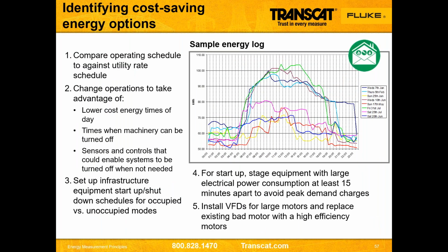So we want to look at a cadence or usage of power. When's my peak demand time? What loads are on or off during that time? What things are cycling on and off, like a compressor, for example? And where could I possibly install things like a soft start or a VFD to reduce the overall, what we refer to as inrush current or startup current, which is peak.